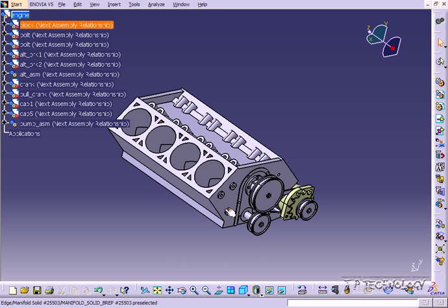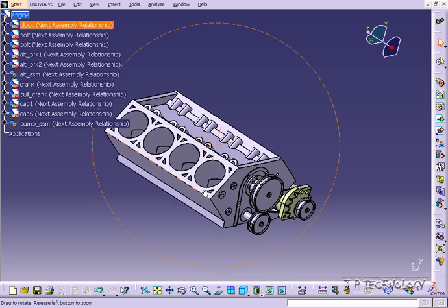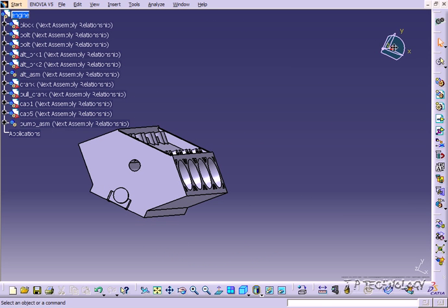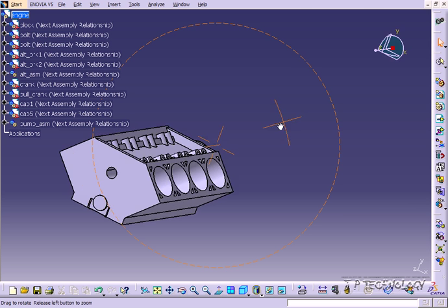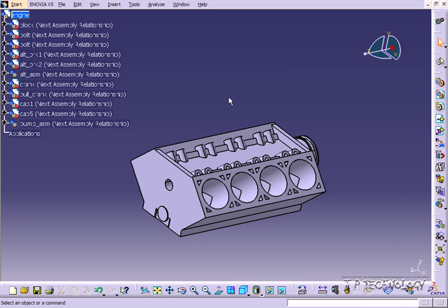And again, I can't emphasize enough how important this is, because if I didn't have an axis there, when you try to throw the compass in there, you're going to get different results every time. To be precise and consistent every time, create the axis that you want to rotate about. You can use an edge too, but if you want to rotate through, say, a circle, get that center circle's axis in there and rotate about that.